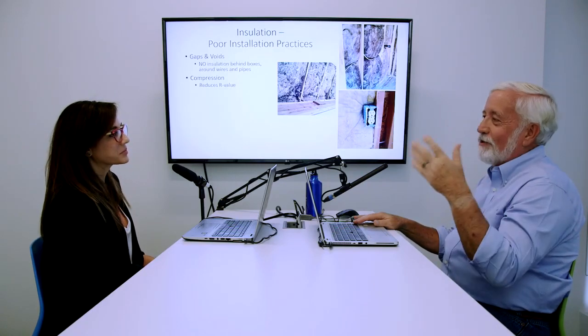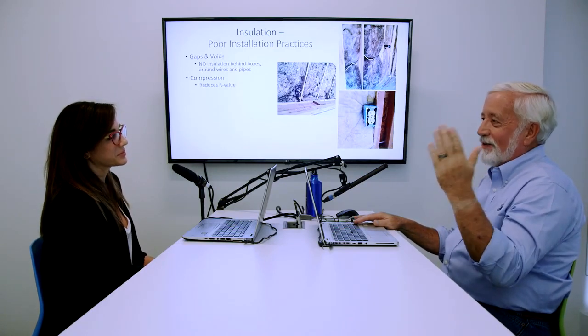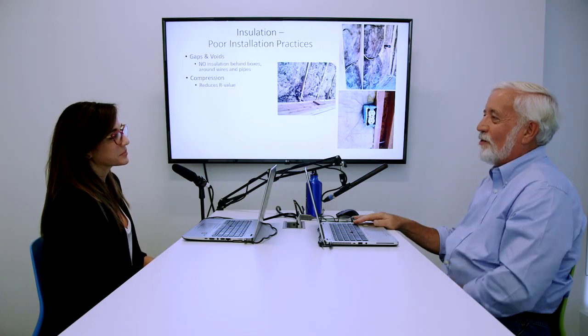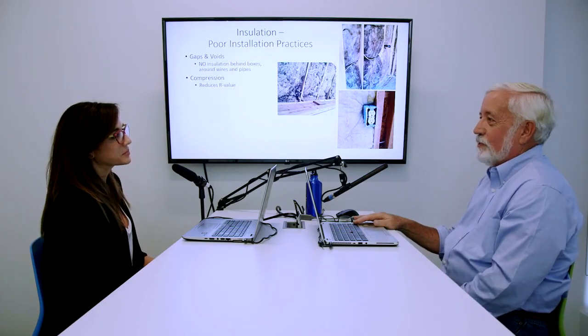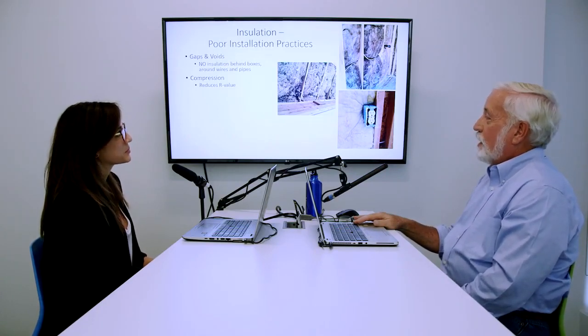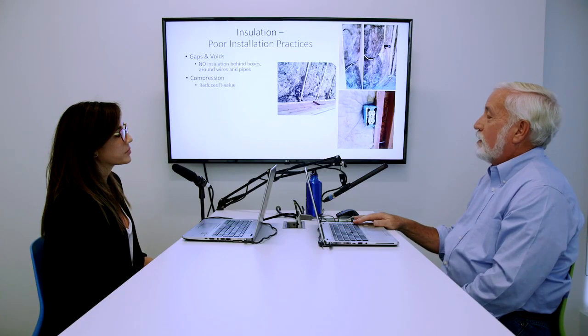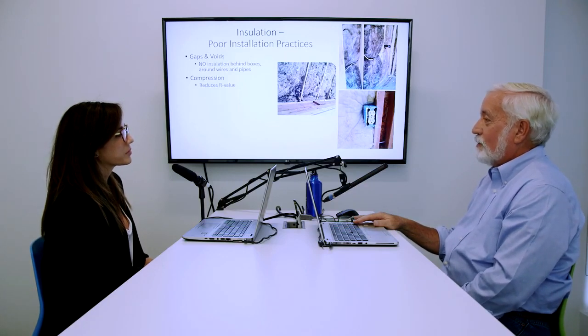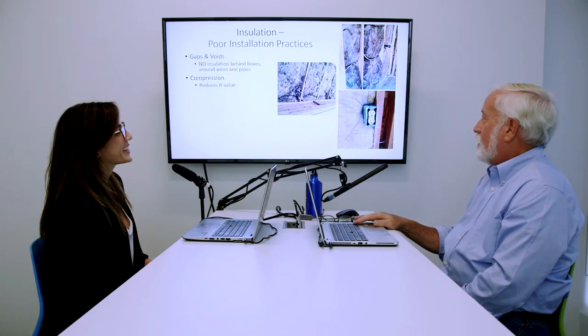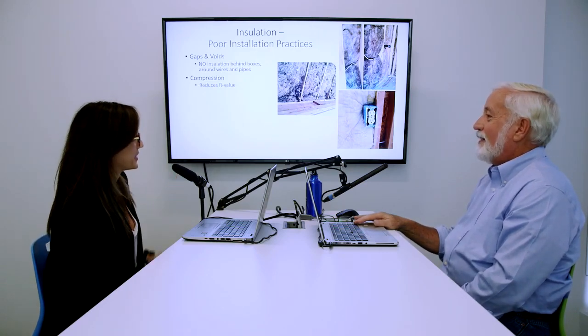Yeah, because I bash poor installation all the time, and our friends that are HERS raters and everything, you've probably heard some of them. They just go off on how horrible the installation is. And it's a crappy job. It itches, and it's not the funnest job in the world. But to do it right just takes a little more effort. They're getting paid by the square foot, and they just want to get it in there. And they do not want to cut anything.